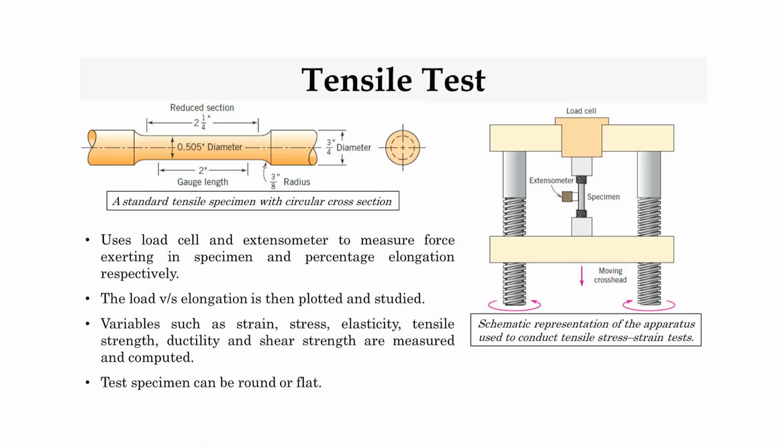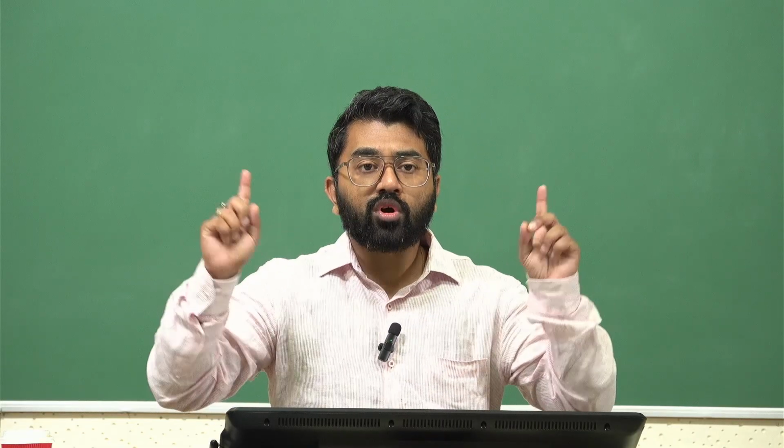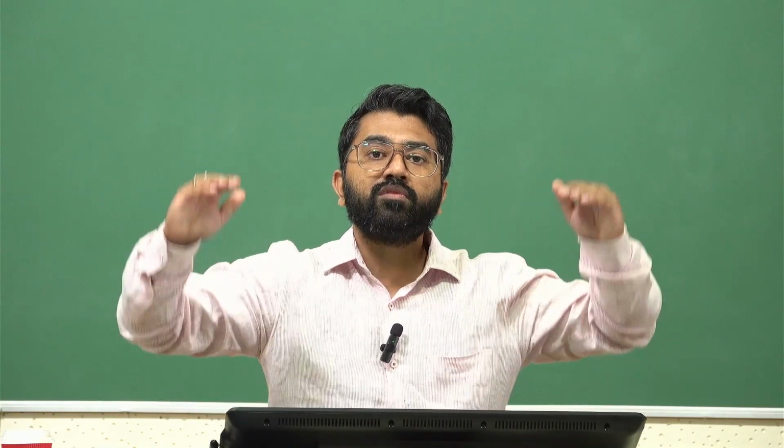There is a load cell at the very top. Let's take a look at the figure on the right, where you are looking at another part known as the extensometer. An extensometer is sometimes used to look at the displacements, but how much the tissue is displacing can also be calculated by looking at how much the crosshead or the gear of the entire UTM assembly is moving.